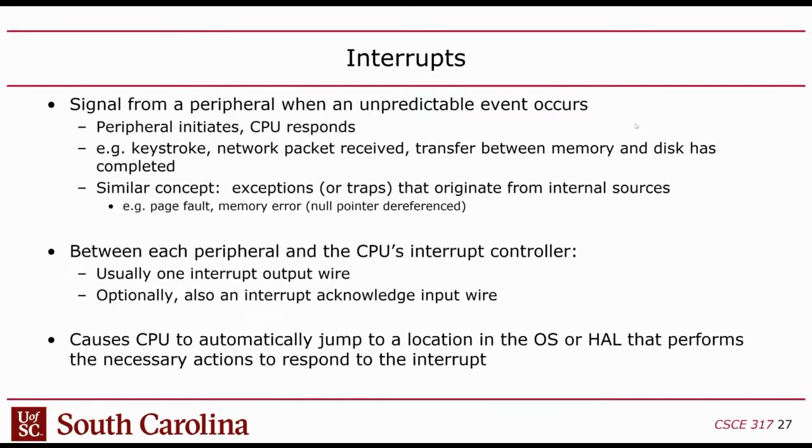There is an interrupt service routine, sometimes called an ISR, that is loaded in the operating system or the hardware abstraction layer, or in the user code if this is bare metal. When the interrupt occurs, the CPU automatically goes there and executes the code. And when it's done, it returns back to whatever it was doing when the interrupt occurred. So this requires hardware support.